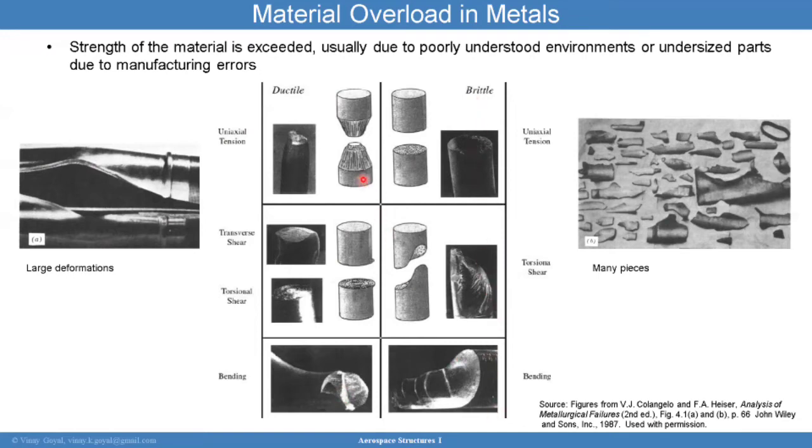And you can see that the failure characteristics for ductile failure are significantly different from a brittle failure. For the brittle failure, if you have tensile loading conditions, you have more of a flaw with very little deformation of the structure. In a ductile failure, you can get a lot of necking, and you're going to have changing characteristics of the cross section.